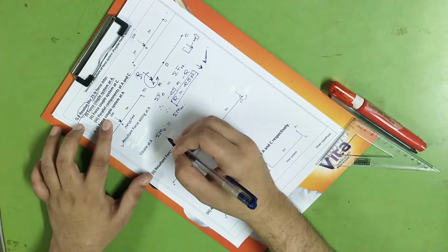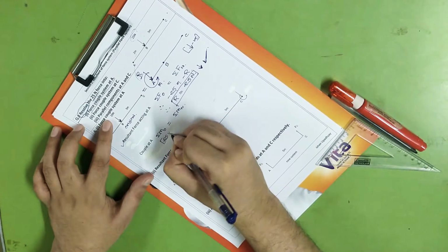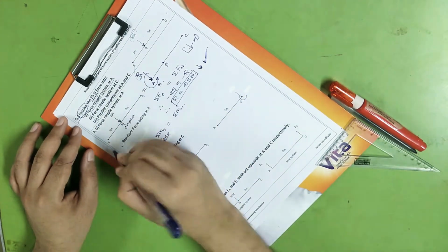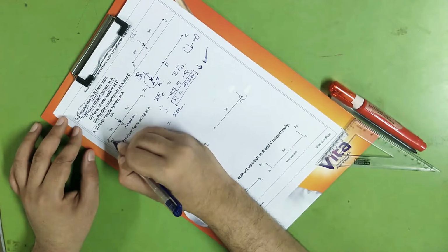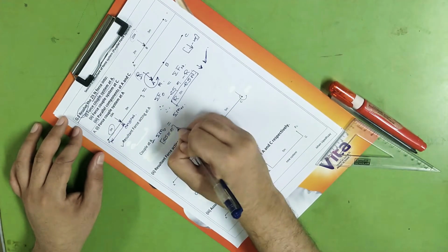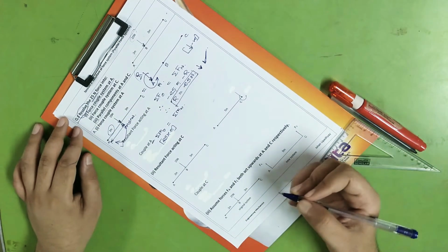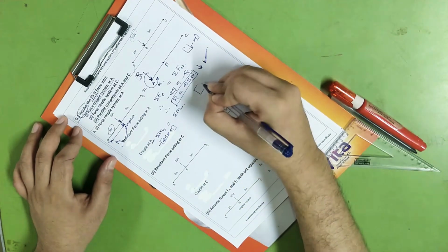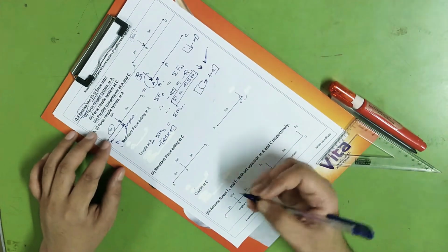First there is a 25 Newton force and that will produce some moment. What is the formula for moment? It is force into perpendicular distance. Perpendicular distance between the force and the point about which I am taking moment. Say I am taking moment about point A, then this length is given as 2 meters. So 25 into 2. Now it is producing moment in which direction? It is producing moment in the clockwise direction. Put a minus sign for the clockwise. For this we have to assume that anti-clockwise is positive, so clockwise will be negative.